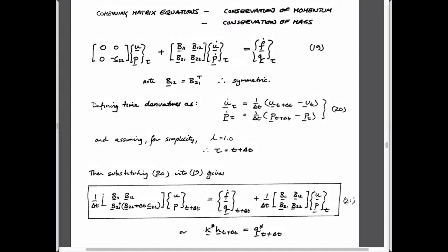So let's take stock again. If we're just looking at solid mechanics, this is our best friend. This is our stiffness matrix. You see that because this is a displacement rate, this has to be a force rate. But since we just differentiated with respect to time, this equation hasn't changed. The two dependent components have changed: rates of change of displacements, rates of change of forces.